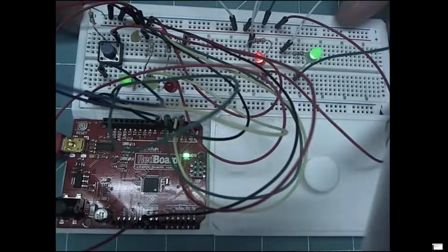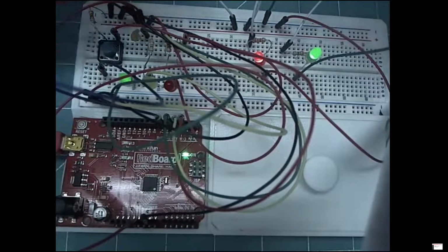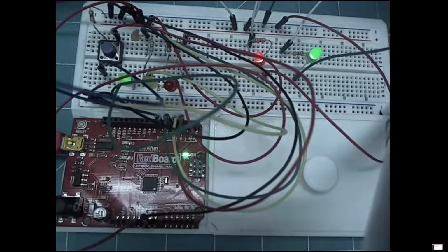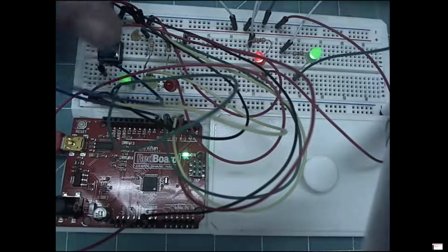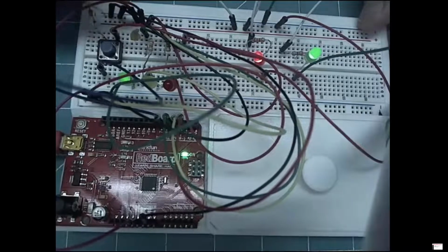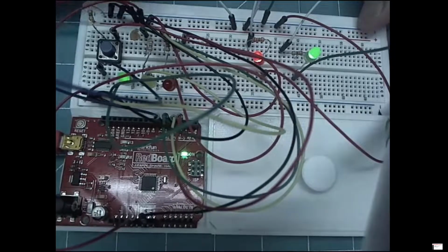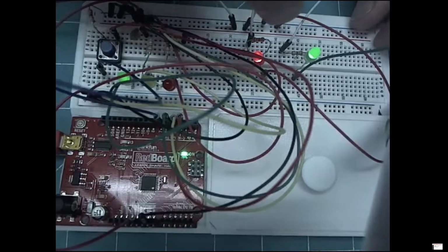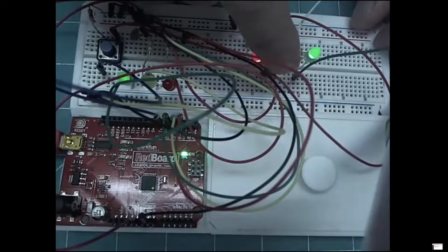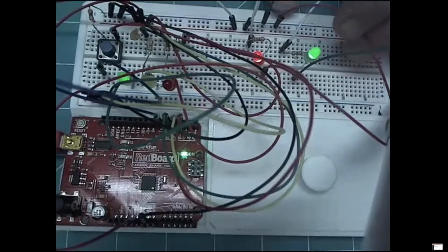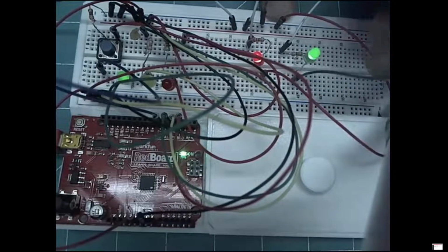As you can see, I have made sure that my negatives were where they were supposed to be and my positives were where they were supposed to be. I moved all the wires back and forth on the power rails to represent where they're supposed to go. So now the LED's cathode is actually going to ground on both of these.